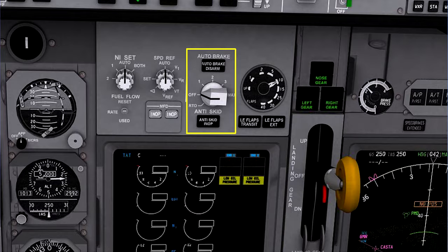Most modern aircraft have an automatic braking system which can be selected to operate during landing rollout or during a rejected takeoff. The auto brake system is usually only usable when the brakes are being supplied from their normal hydraulic source. It is not normally available when using the alternate brake system. The main advantages of such a system are that it will react more quickly than the pilot, and will also constantly apply the correct amount of braking to provide the required rate of deceleration.